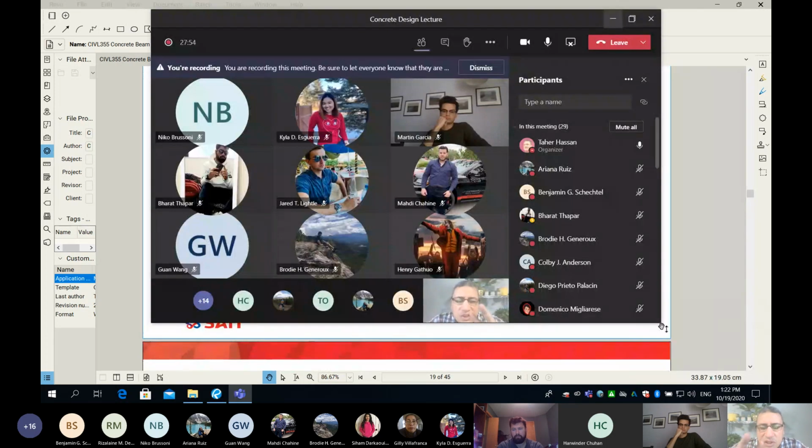Guys, look at this. There are 2 situations. One is design. The other one is a check. Check means you have an existing situation. So the beam is already built. And my job is to say the beam can survive or it cannot survive under the new loading. You know what? If the problem is a check, I will justify and I will use my skin reinforcement to add extra capacity to my beam, because the reality is it will do that. However, in my design, I'm not going to bother.